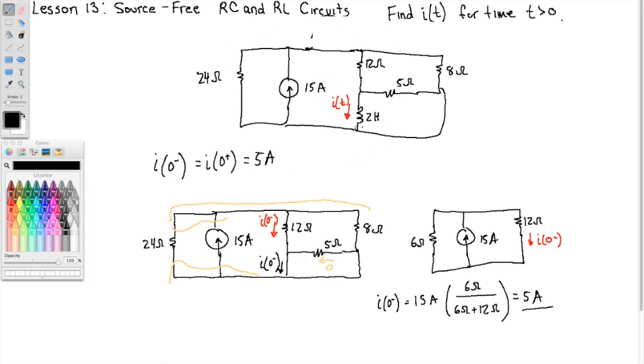All right, well, in the original circuit, the switch was right here. So let's open that switch now, because we're talking after the switch. Let's identify the nodes. Can we combine anything? Here are the nodes of the circuit. No current goes this way because it has no return path.